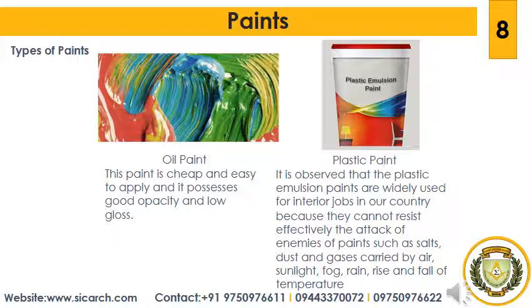So these paints are usually supplied with thick consistency, and for diluting the paints, the instructions given by the manufacturer should be strictly followed. In a general way, it can be stated that half liter extra water will be required for the first coat and quarter liter extra water will be required for the second coat.